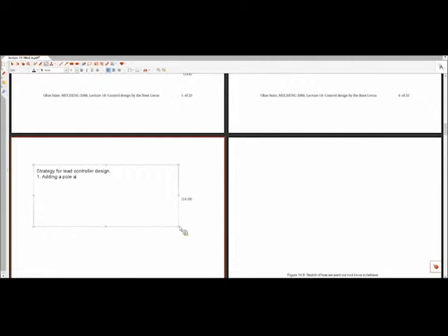So adding a pole and zero pair, where the pole is larger in magnitude, will drag asymptote sigma A to the left.